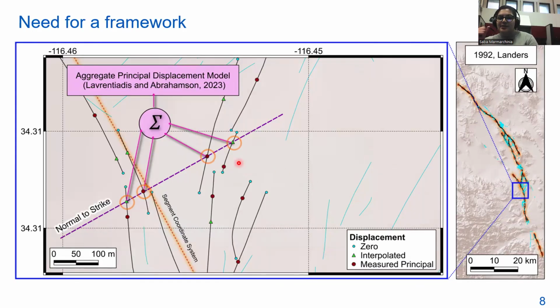Aggregate displacement is the sum of individual principal displacements happening on individual ruptures. Defining the hazard for aggregate displacement would be the case where the structure crosses all of the overlapping ruptures. But since these ruptures can be kilometers away, aggregate displacement may not be the exact displacement demand. So we need to convert from aggregate displacement to individual displacement.